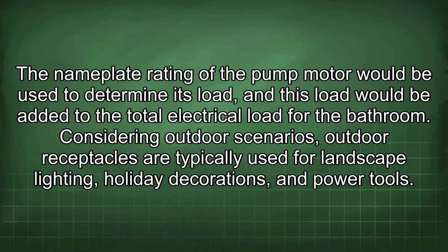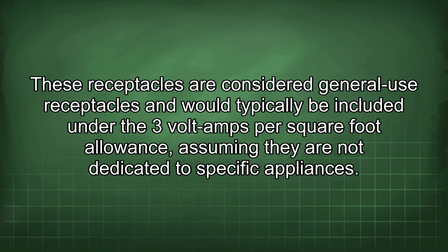Considering outdoor scenarios, outdoor receptacles are typically used for landscape lighting, holiday decorations, and power tools. These receptacles are considered general use receptacles and would typically be included under the 3 volt amps per square foot allowance, assuming they are not dedicated to specific appliances.